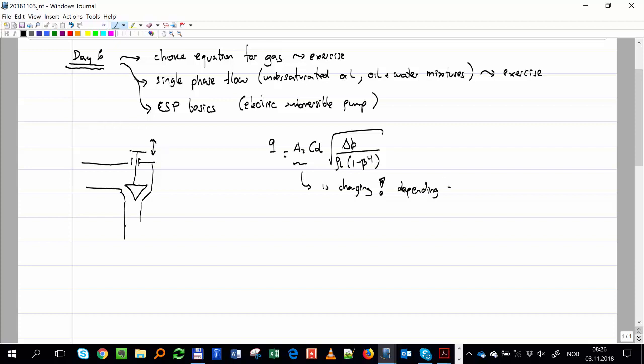The position of the valve stem, which we are going to call L. So area 2 is a function of L, depending on how high this is. If it's very well separated, that area will be very big, and if it's lower, that area will be very small.